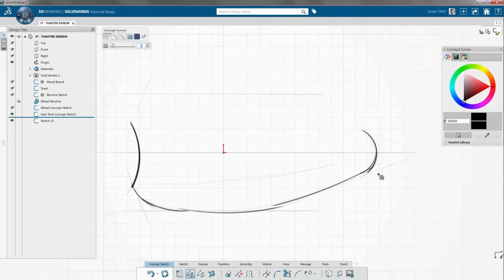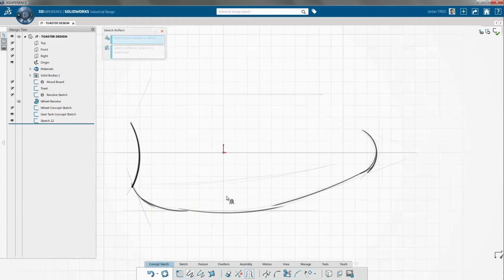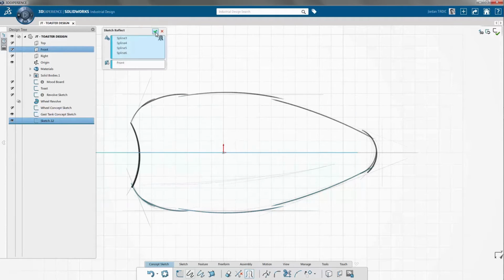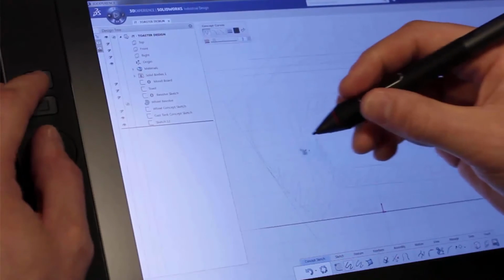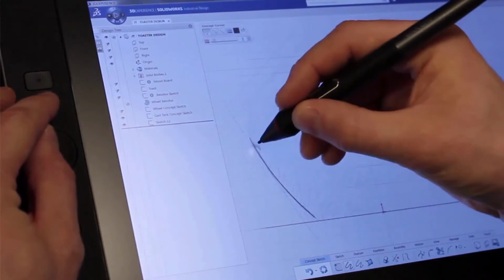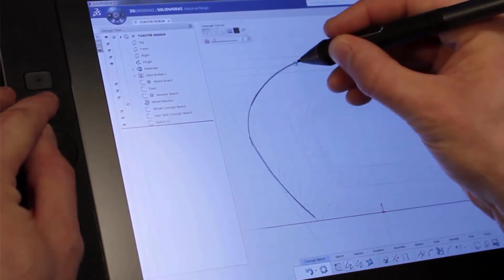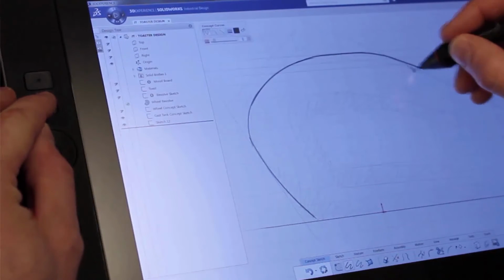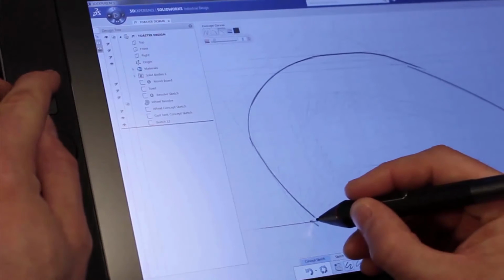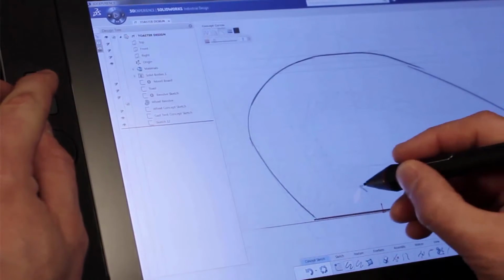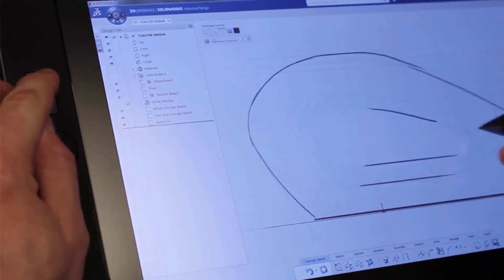One of the benefits of sketching digitally is that we can take advantage of CAD-like operations such as a smear command. Just a few more strokes on this top plane, and I can flip right back to the side view. Holding the Alt or Shift keys, SOLIDWORKS Industrial Design can assist my limited sketching skills by converting my strokes into perfect radius arcs or perfectly straight lines.